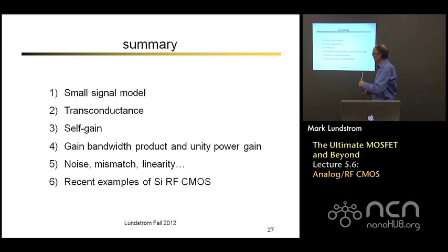And then there are other considerations that we haven't had time to discuss in detail. But as that example shows, you're seeing more and more applications of silicon RF to various applications using conventional CMOS, not only for digital but also for analog applications. But for the most demanding high-frequency applications, designers will still rely on III-V transistors, either HEMTs or HBTs, which can offer frequencies of operation that are factors of 2 or so higher than you can get from very small silicon devices. Okay, so that wraps up our discussion of circuits, both digital and analog.